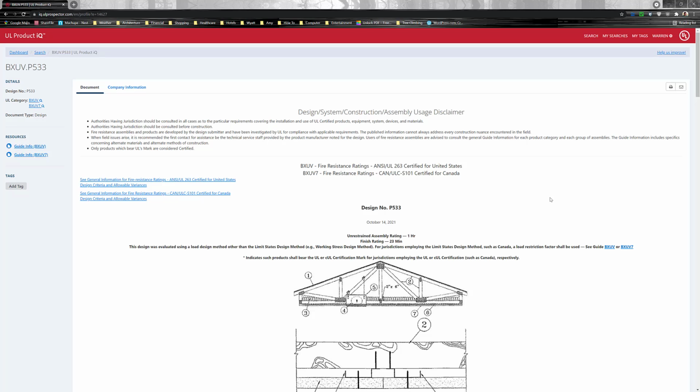performance rating. So they have their own very special UL assembly, and really the only thing that makes it special is that, for example, on an exterior wall they require you to use mineral wool or some other additional fire resistant material. I can't name all of them, but I know rock wool or mineral wool is one of them, instead of being able to use fiberglass batts.